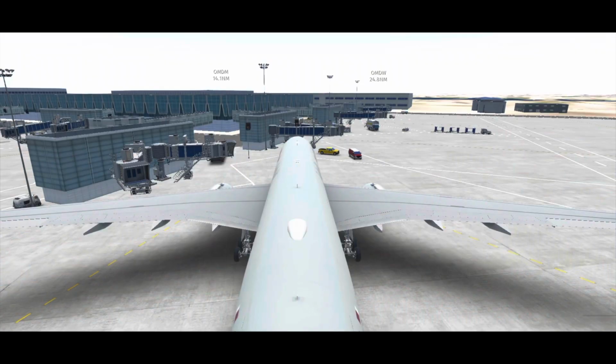Now the flaps are controls or devices used on an aircraft for high lift, which are attached to the trailing edge of the wing, increasing both lift and also induced drag for any given angle of attack.